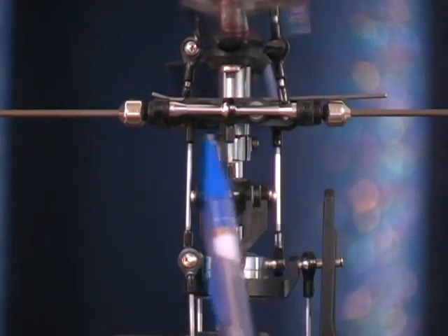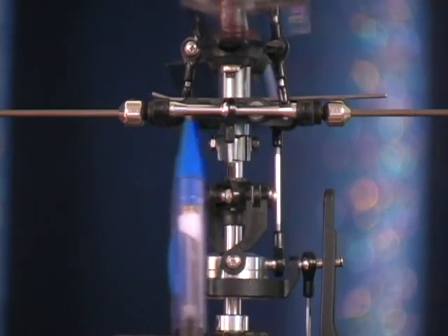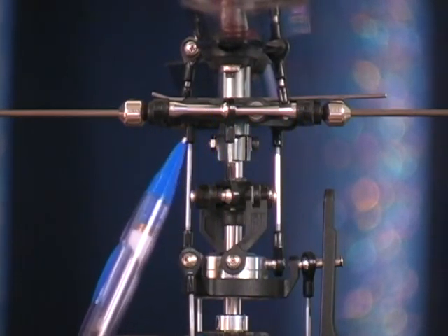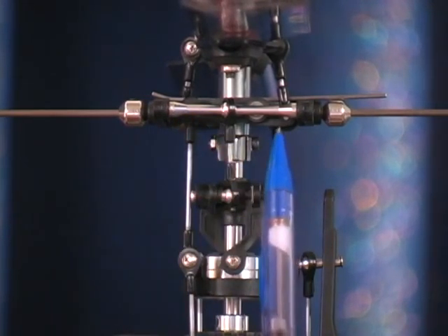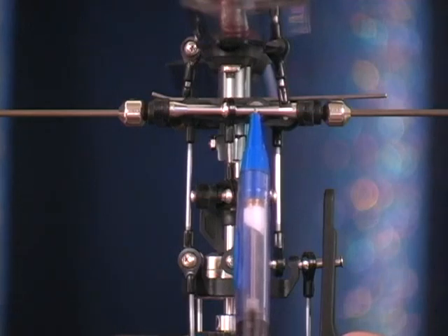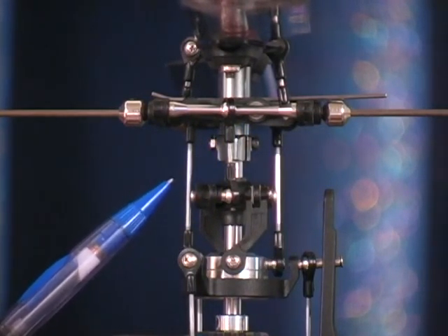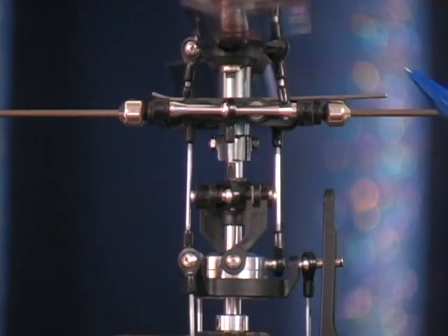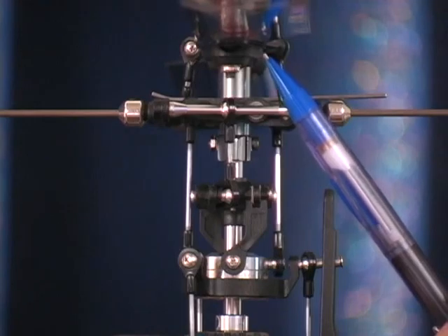Next, we want to make sure that the mixer arms are level. The flybar birdcage kind of obstructs the view here, but basically this ball link should be level with the rod, and of course this screw is level with the rod. And then if the mixer arm is not level, just adjust this push rod first, and then come back and adjust this push rod to keep 12 degrees of pitch at full stick.